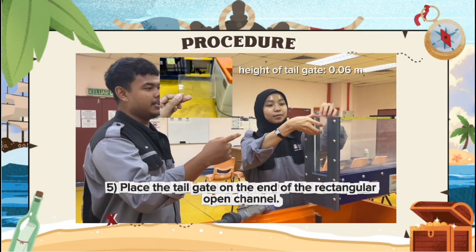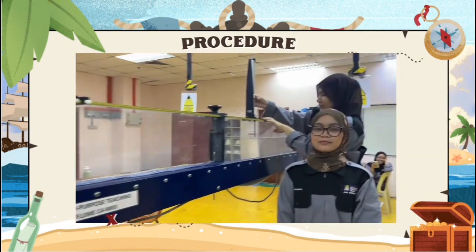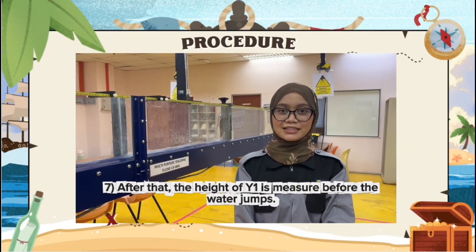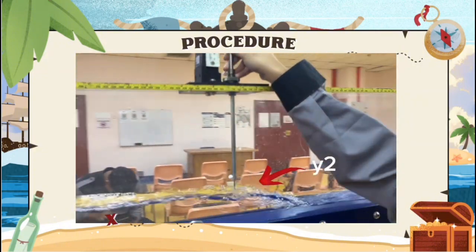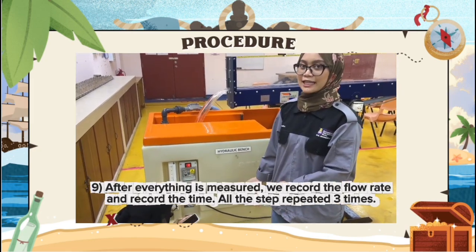And then place the tailgate at the end of the rectangular open channel. After the water is level, we measure the height of Y. After that, the height of Y1 is measured before the water jump. After that, the height of Y2 is also measured after the water jump. After everything is measured, we record the flow rate and record the time.